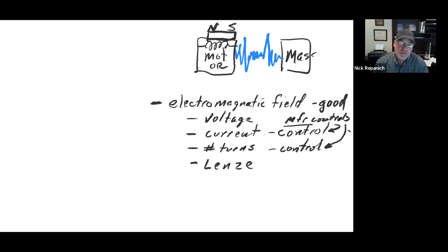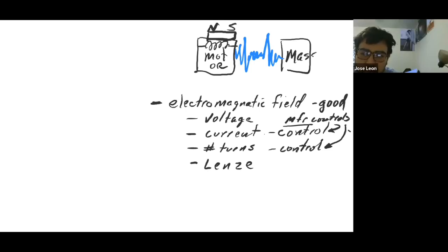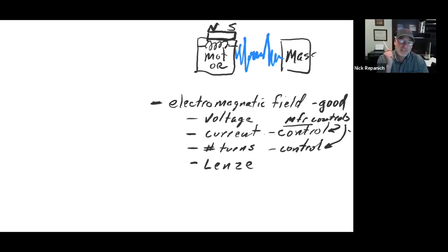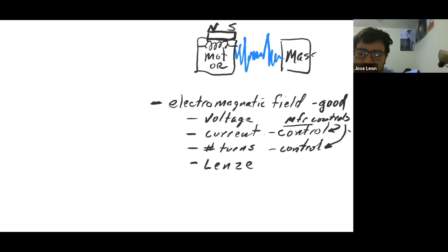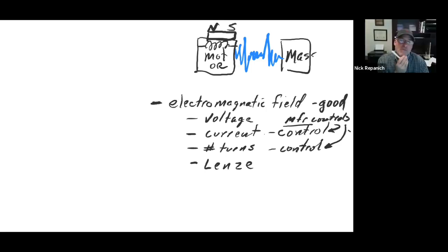But what happens as soon as you start to change the current in the winding? What do you get? An induced magnetic field out of the current that's changing? Kind of. Do you remember that word, back EMF voltage? You ever hear that? Back EMF voltage?